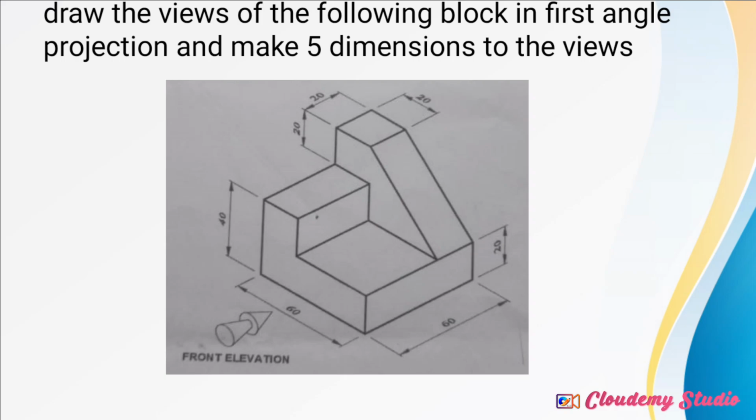And if you consider the front elevation, what you can be able to see is that L face that looks like an L. Then we have that hind face that looks like a triangle. So those are the 2 faces that you'll be able to see. If you look at from the end elevation, and if the question has told you to consider the front elevation as that, then on your right hand is always the end elevation, if you have not been given.